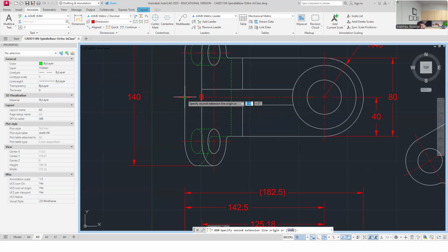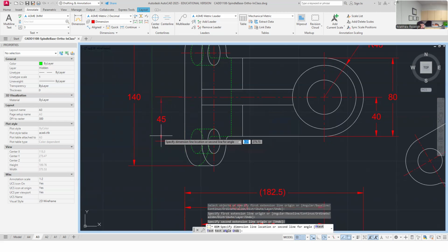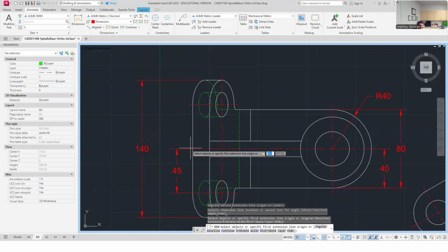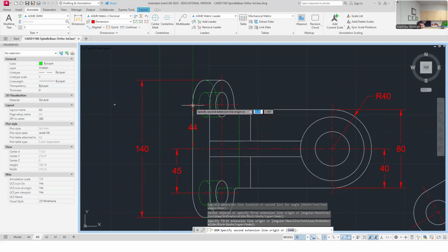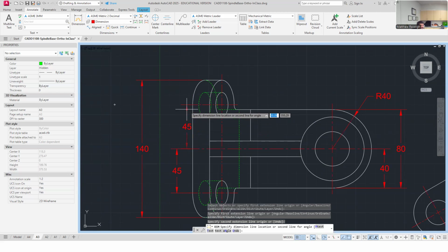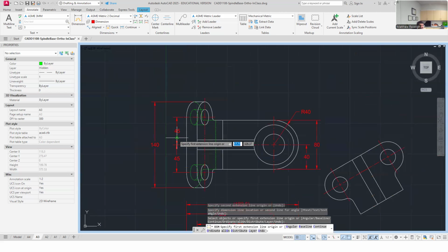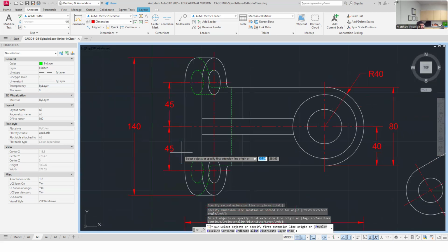I'm going to pull this from here to here. And really what I'm actually thinking of is that's kind of where the outer radius of the part starts, because I haven't defined its shape yet. And the shape contour of it starts right there, 45 over from center. And I'm going to do that over here, so I can't assume that somebody thinks that it's totally symmetrical unless I had a note that said symmetrical through center from front to back or something. And those notes are tricky because then you're under dimensioning stuff and people have to read your notes. And so sometimes the dimension on the thing is better than a note in a list.